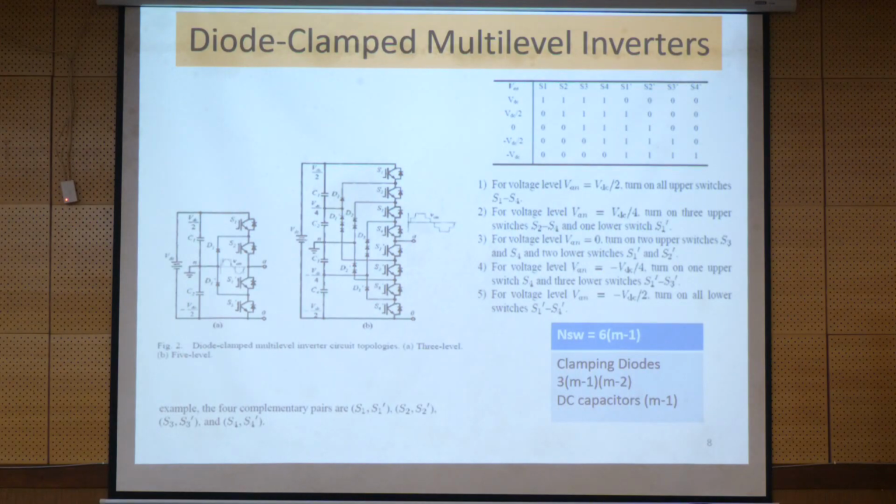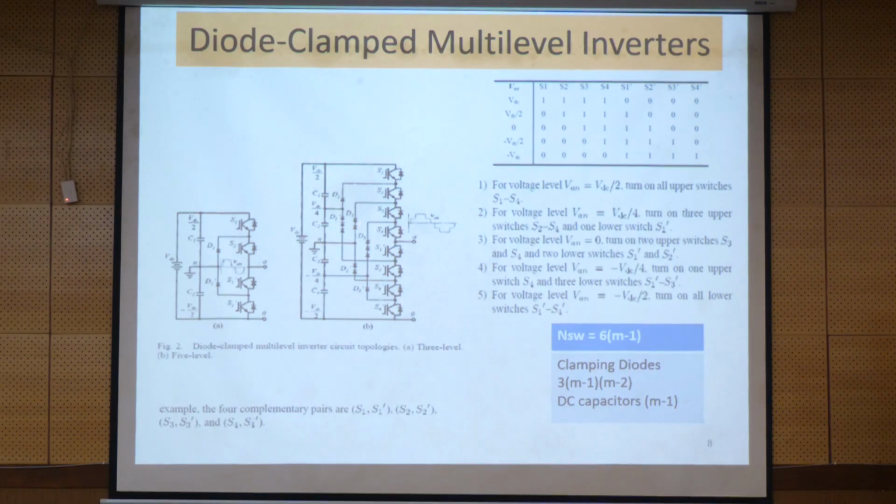Then the other thing, the diode clamped extension for this 3-level, 5-level, means more diodes are going to be there for each leg configuration. This makes it more complex. For the 5-level, at any instant of time 4 switches are supposed to be on. These are of complementary function. One we are getting for the line redundancy and the phase redundancy.